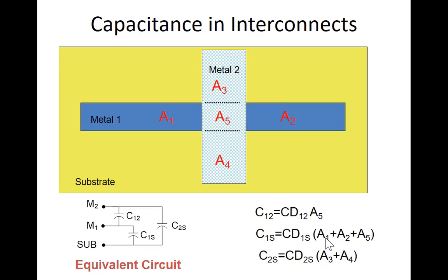No, it might be very high. This distance is pretty large. So this is all insulator in here. So there's insulator on top of metal 1, an insulator below metal 1. The insulator is necessary to separate metal 1 and metal 2. Okay. So there's only one thing, it's called a substrate. That's the silicon wafer we started with. On top of that, we put an insulating layer. On top of that, we put metal 1 and patterned it. On top of that, we put another insulator. On top of that, we put metal 2 and patterned it. Okay? That makes sense. Good.